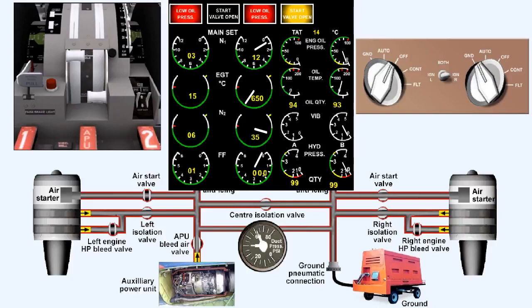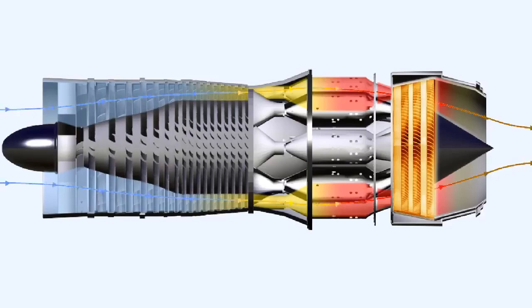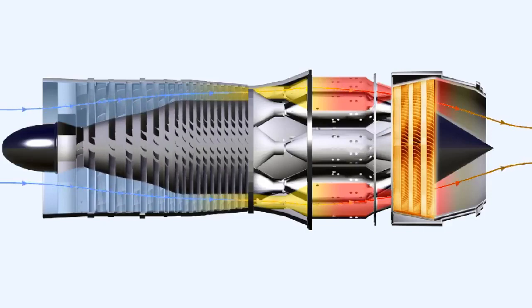Waiting for instructions or discussing the indications will almost certainly cost you or your company the price of a new engine. Hence the advice to keep your hand on the fuel supply control. If the EGT exceeds the limit by only 1 degree, the engine is to be considered unserviceable. The reasons for a hot start lie almost entirely in having either too much fuel or not enough air to cool the gases through the turbine.